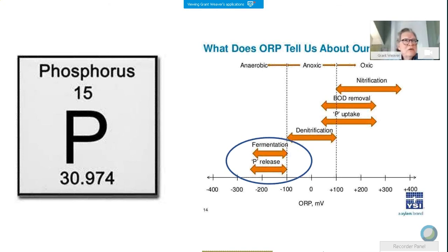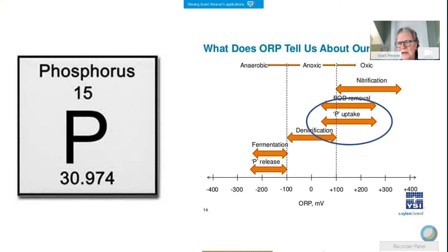And when I say these numbers, they're always subject to change based on your conditions. It's a good place to start. And then as you get a better understanding, a better control, you can refine those numbers for your facility. Minus 250 might be a better number for you. Minus 300, minus 125, probably not as low as minus 125, probably more negative than that. So there's one condition, septic condition, just short of creating methane gas. So you're almost fully anaerobically digesting, just short of creating methane gas.